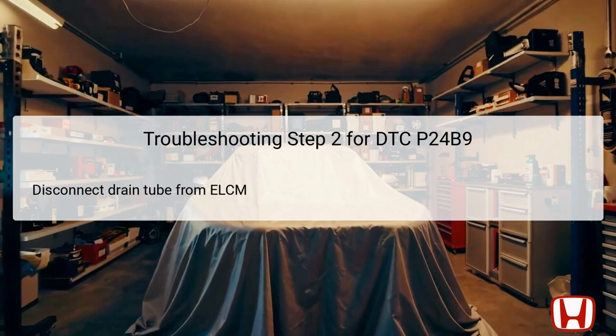In this step, the technician disconnects the drain tube from the Evaporative Leak Check Module, ELCM, to facilitate further diagnostics. This step is vital as it allows access to the ELCM and enables a pressure test to determine the integrity of the system. By disconnecting the drain tube, the technician can ensure that any blockage or malfunction in this component is isolated, thereby narrowing down potential causes for the DTC. It is essential to handle this component carefully to avoid any subsequent damage.